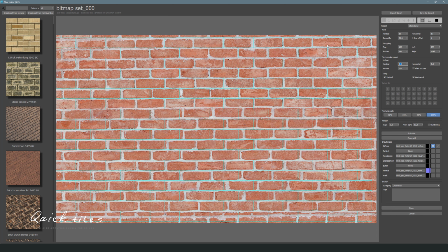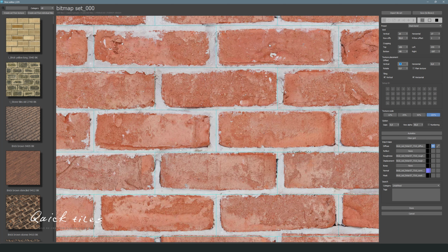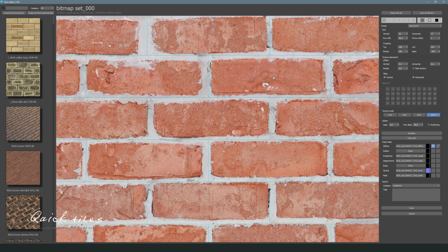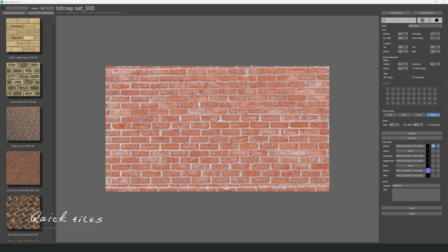Fine, the upper rows are more or less leveled. And for us at the moment this is enough. Now in each cell QuickTiles will see a separate tile. But what about the gaps, you ask? For the designation of their thickness, there is a gaps parameter. We add a value greater than 0. And the thin blue lines immediately expand and capture the gaps. Thus, we have created an ideal grid that does not fit almost any natural texture.